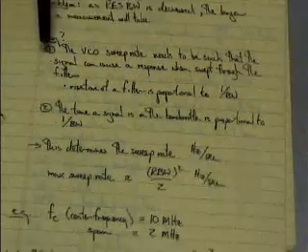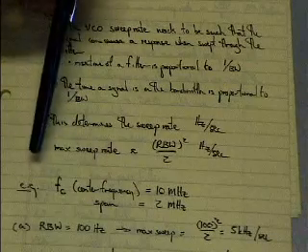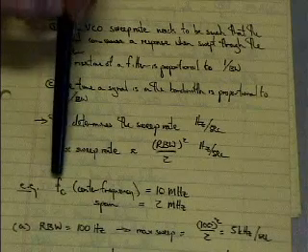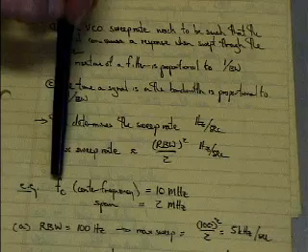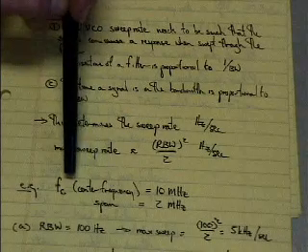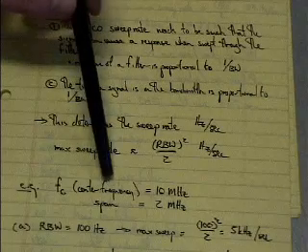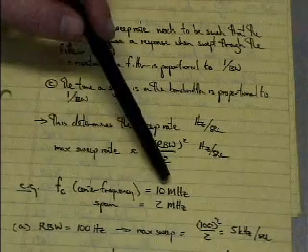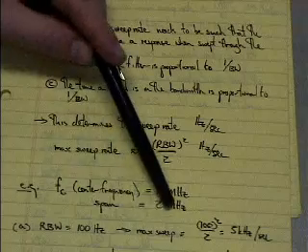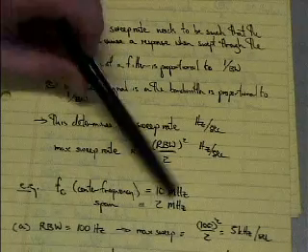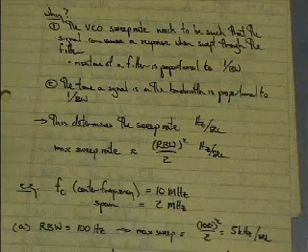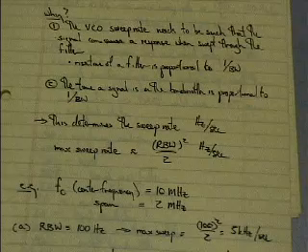Okay, so let's look at an example of what we might have here. We have a signal that we're interested in, and we're going to set up the center frequency, that is, the center point of the spectrum analyzer, to 10 megahertz, and we're going to set up a span of 2 megahertz. That is, I'm going to be looking at a 2 megahertz chunk of the spectrum, and I'm going to be sweeping across it.